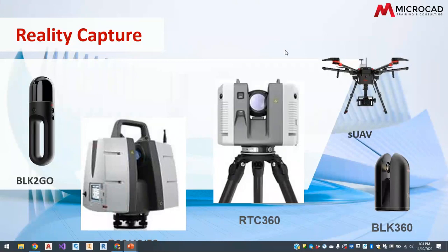Thank you, Mike. Next question is, what is the maximum time for a scan with the maximum resolution? For a single setup at max resolution, the RTC 360 is probably around 7 minutes, where the P series would be upwards of 13 or 15 minutes at a max resolution scan.